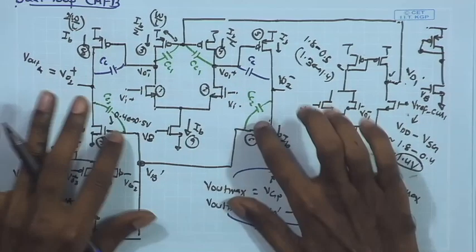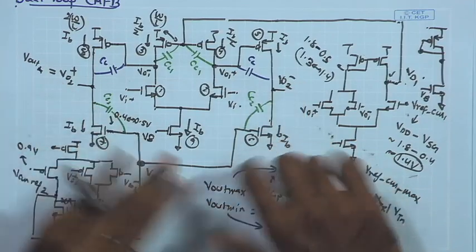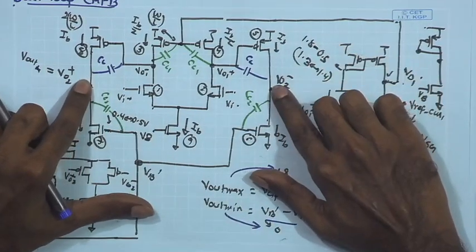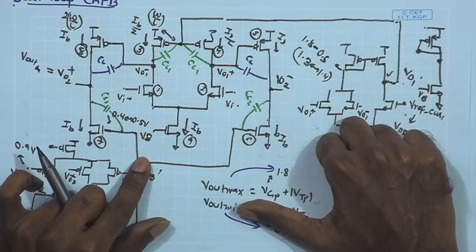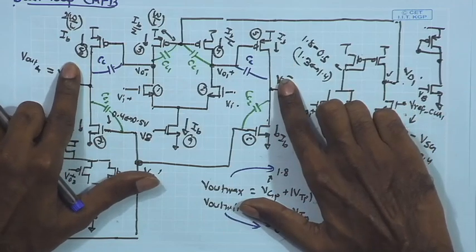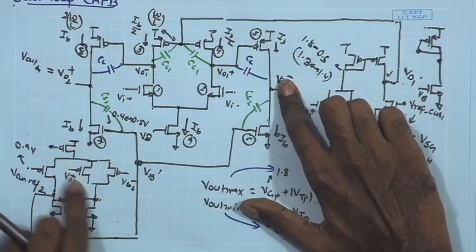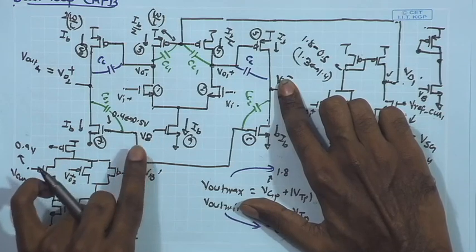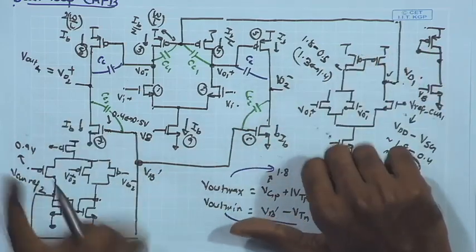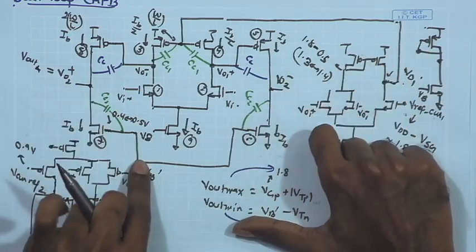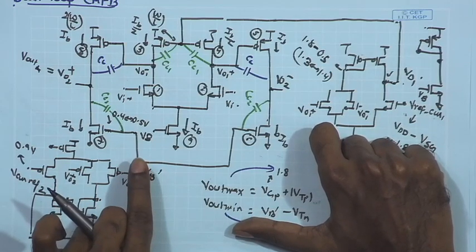Likewise, if I look at the CC2 over here, they are also following the same argument that the overall differential signal over here is large, but as a result of this, the common mode signal over here is not going to be very significant. If the signals over here are differential and the common mode at the input is not changing significantly, then the output DC bias point provided by the second common mode feedback amplifier is also going to be relatively constant, and as a result this is going to appear more or less as a DC bias point and hence an AC ground for the differential operation.